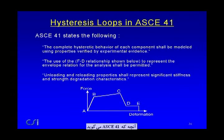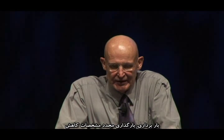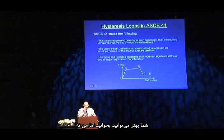What ASCE 41 says is the following: the complete hysteretic behavior of each component should be modeled. And the use of the F-D relationship shown below shall be permitted. And unloading and reloading shall represent significant strength and stiffness degradation characteristics. You can read better than I can.